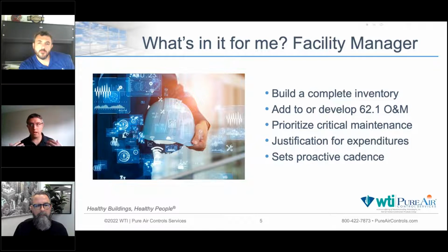And I explained to them, you guys have a lot of air handlers on a lot of floors. Rather than just immediately, if something comes out of the duct, go right in there and clean, it's going to be critical going forward that you start to get all these units assessed and inventoried, because this may not be the last time this happens. Let's get you a plan together, because you ended up coming back and re-cleaning and putting a lot of money into this when, if we prioritized that critical maintenance and what other issues would be found in the air handler, also causing other issues, clogged coils, some drain pan leakage, we could be ahead of this and stop a lot of these problems before they occurred.